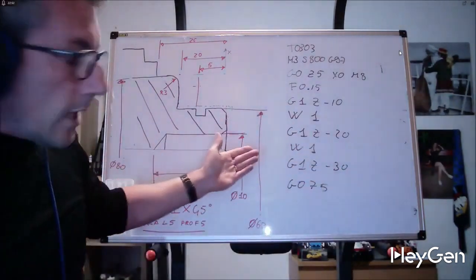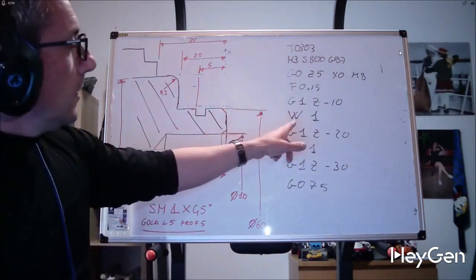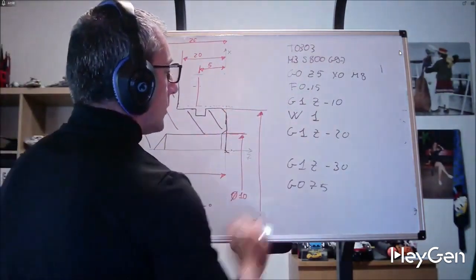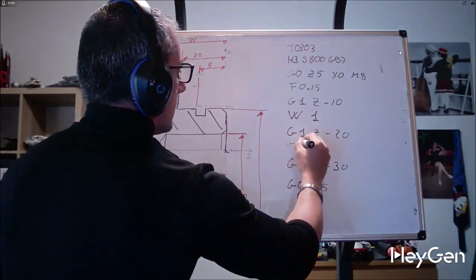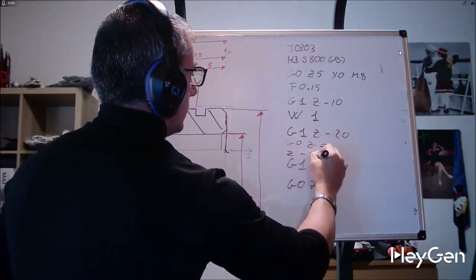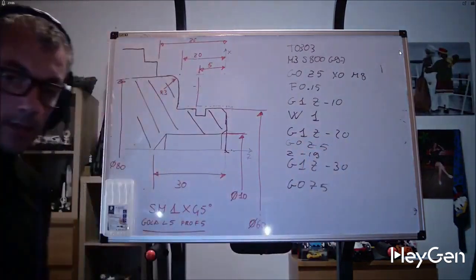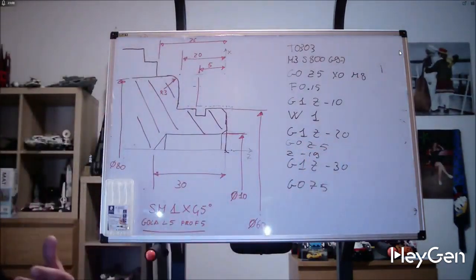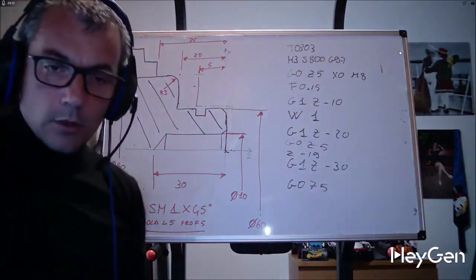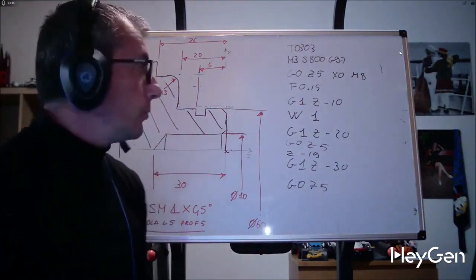We could even exit the piece, that is, instead of V1, let's do it here instead of V1, we could put G0, Z5, Z19 here and then start. I mean to really clear the chip, because at the tips, the chip sometimes doesn't break, it gets in the way, and when the chip doesn't break, what breaks is the tip.